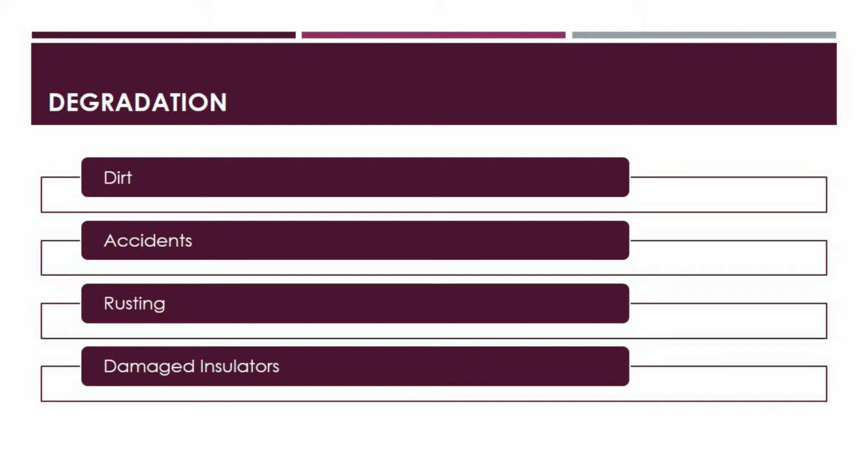Other flaws are significant and demand attention, but they do not cause failure and can be corrected in the field also. Graffiti on switchgear, for example, is typically regarded as an eyesore and may even obscure vital safety and operational signage. So it is normally possible to repaint the outside of the case and replace the signage without interrupting power flow or conducting an outage for that. Anti-graffiti paint may also be an effective remedy in regions where graffiti is a recurring problem for these switchgears.